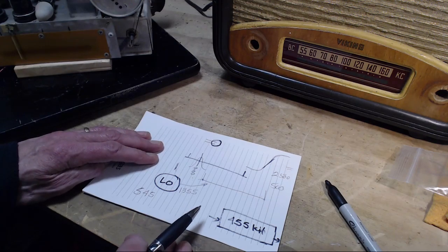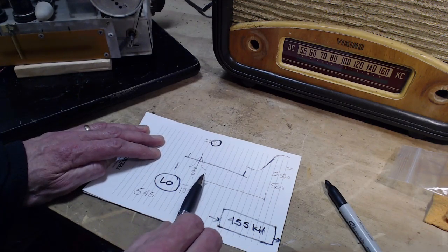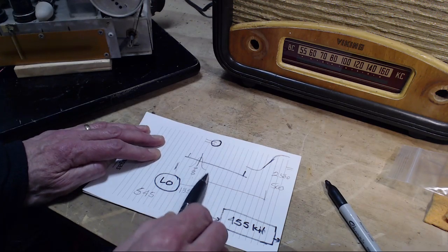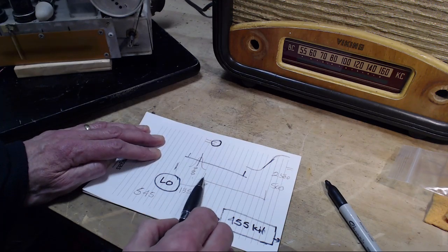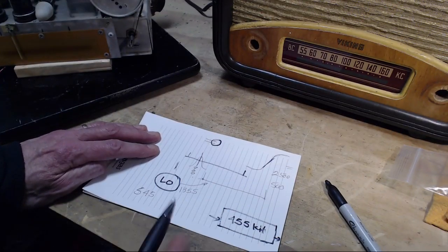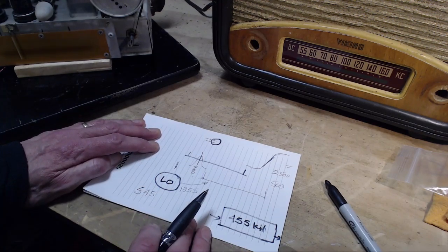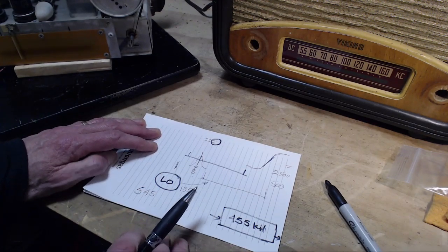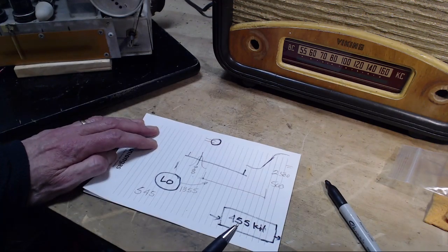Yes, and you can tune the radio that way, and different radios have the local oscillator in different positions. Some may be above the target signal, some may be below the target signal. Normally it's above, because there's less chance of problems. I won't go into that any further, but normally it's above. So where's the image on here? Where's this image thing, this image problem? I haven't drawn it yet.